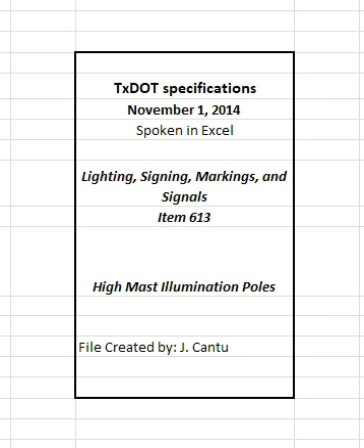1. Adjust pole diameter if shaft thickness exceeds nominal thickness by 0.02 inches or more. Change the splice length for this adjustment. 2. The department may accept an excessive twist for individual pole sections, provided the top of pole is within twist tolerance for assembled sections. 3.4 Installation.